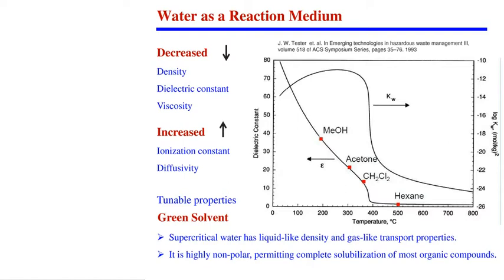So to open up the structure, to make grassy material into ethanol via the fermentation route, we do pre-treatment first. Water can be used to do pre-treatment. So hydrothermal pre-treatment or subcritical water can be used. Once we do the pre-treatment, we can open up the structure, and now enzymes will work better. So why is pre-treatment required? It determines the rate of production or yield of monomeric sugar, glucose, which will be fermented. So subcritical water can be applied here for the pre-treatment application.